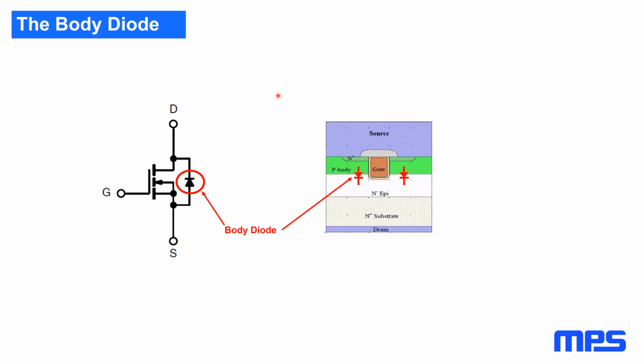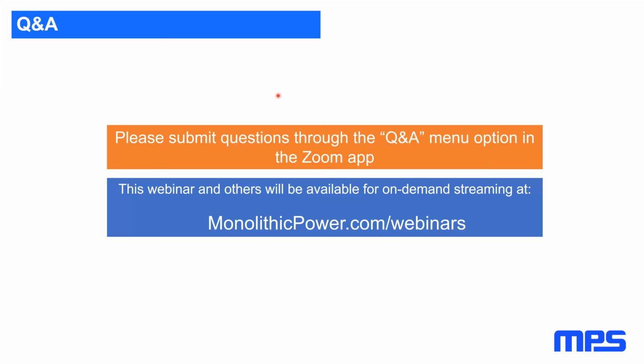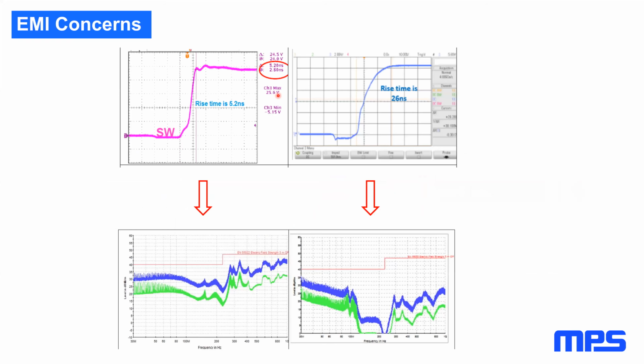Great, thank you. How to calculate power loss in a MOSFET? There are different components. Usually the dominant one is just current times RDS(on), I squared R. That's usually the biggest piece. In addition to that, you need to add in the switching loss, which is a function of switching time, current and voltage.